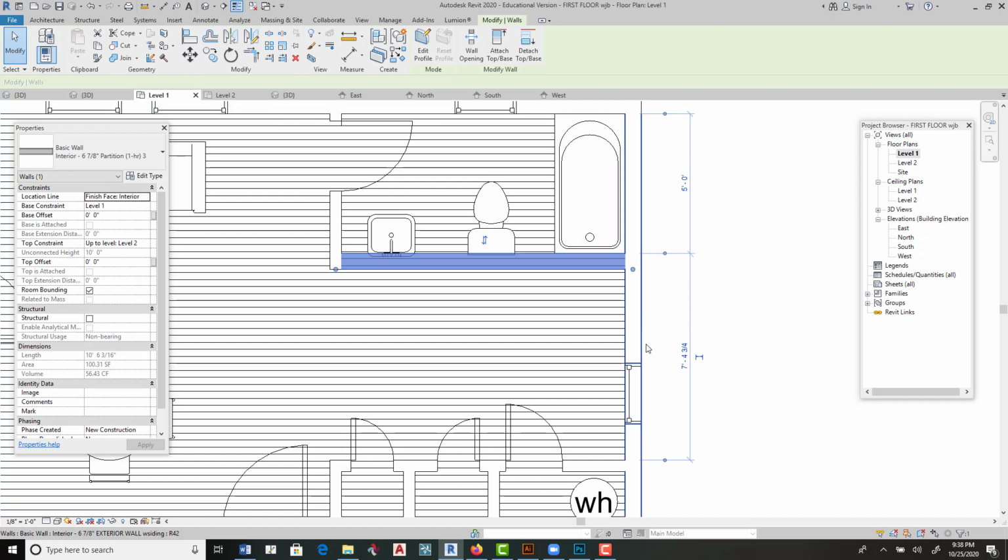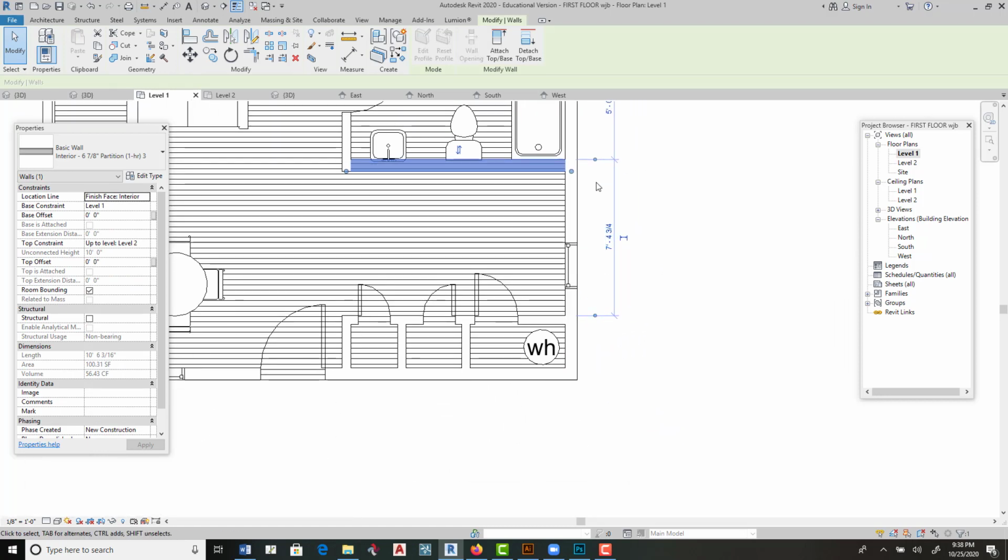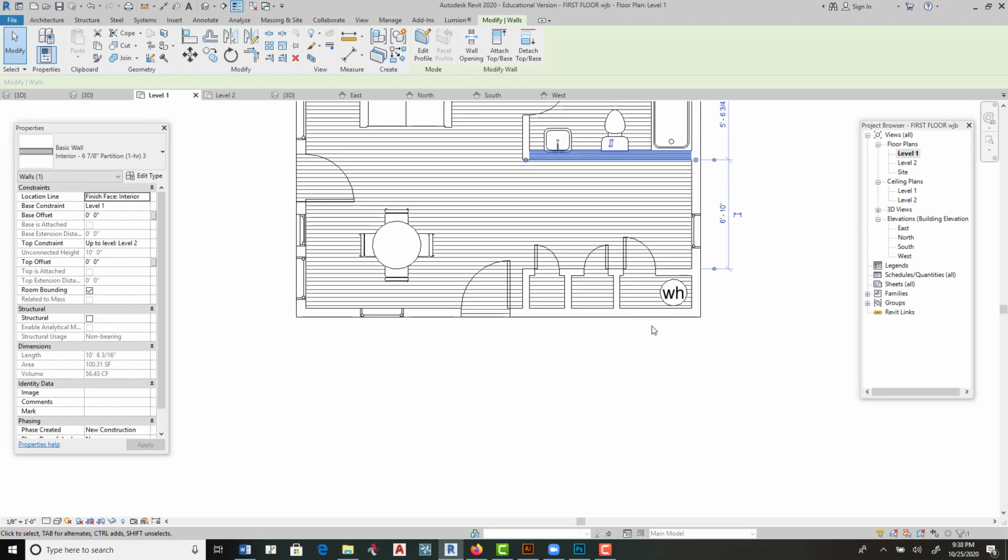Remember, make sure this wall is 5 feet from inside to inside, and make sure this wall right here from inside to inside is 6 feet 10, because we're dealing with cabinets, and you can work on a nominal size.